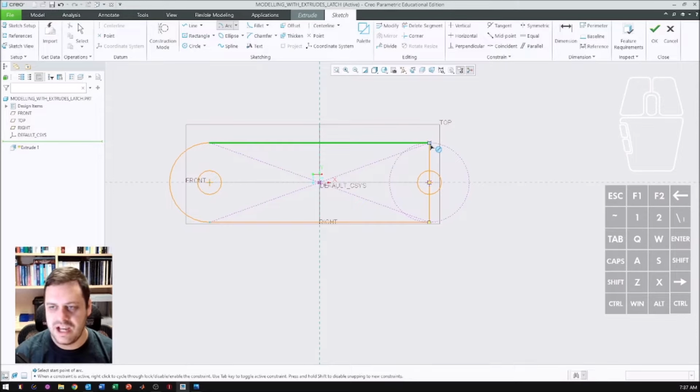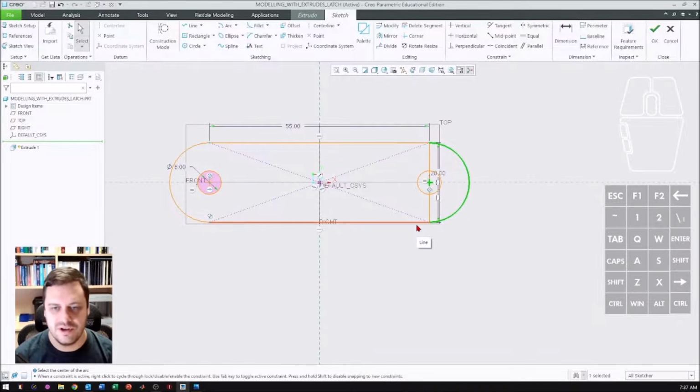And you'll see that we've got a dashed line where it is going to create the circle, similar to what we created to the other side. But once you pick up this particular point that you can see I've got highlighted here, if we left click there and then drag around, we're going to just create half a circle this time. Then we snap to that point there, we can left click again and then center click out. And now you can see that highlighted section, we've got that semicircle. Honestly, it doesn't really make much of a difference in terms of this particular object which way you want to go, but certainly either operation will get you there.